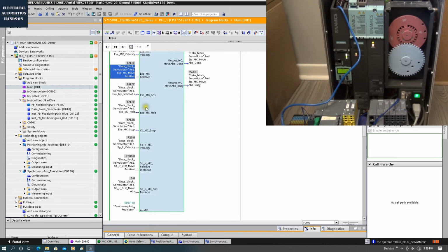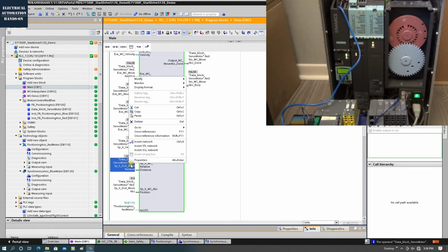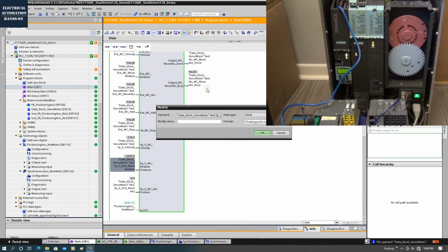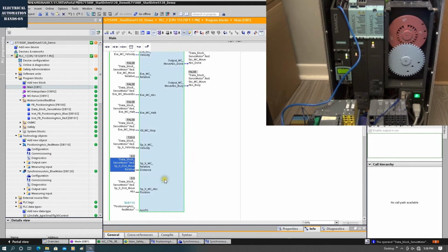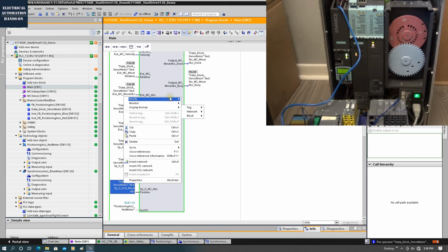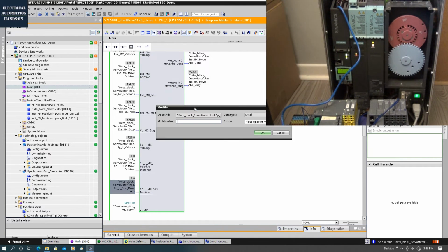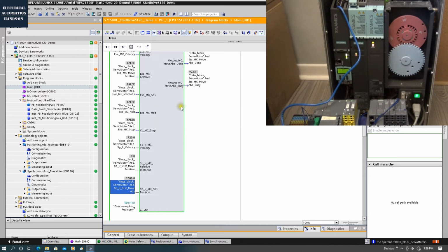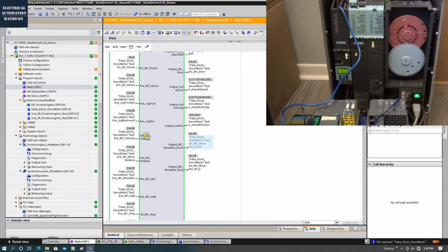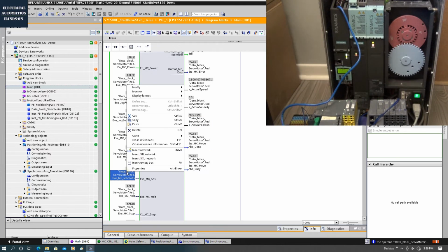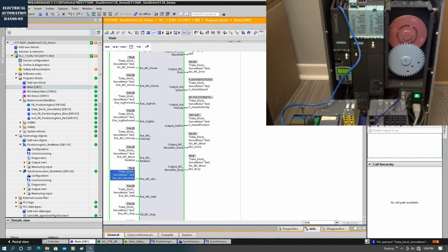And now let's try the MC absolute. Okay, I will set the relative to 0. Now for this MC absolute position, let's drive to 2000. Then let's trigger this execute MC absolute, and meantime watch this output. Drive. Okay, we can see it has acceleration and deceleration.